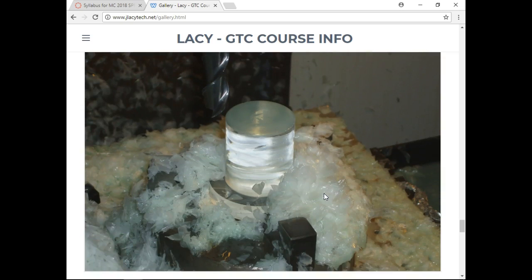And then one of the machine projects we did, well, that's been a long time ago. Piece of acrylic for was a vacuum gripper, and had a LED backlit array so that we could pick up wafers and present them to an industrial camera to do the inspection, and the LEDs had to be able to go through the gripper with minimal amount of shadow. So that was the finish from the tool coming off the machine. That was no polish, no flame, no nothing.